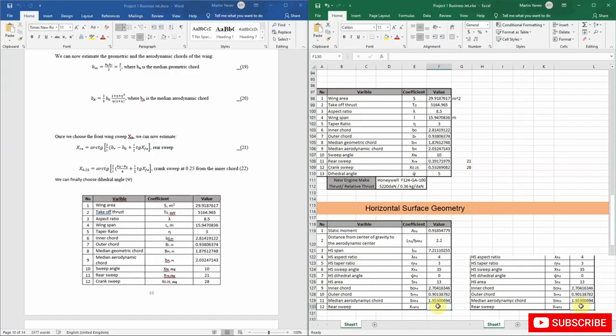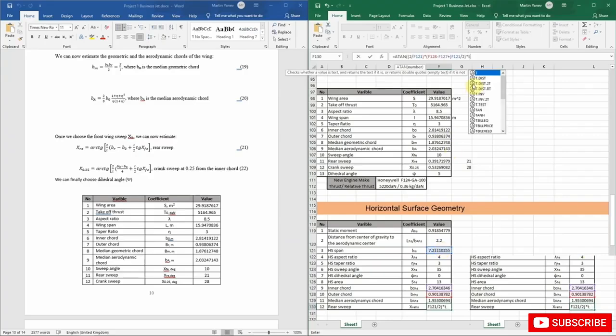So the rear sweep, as from the equation for the wing, will be equal to arccotangent, so a tan, and then in the brackets 2 divided by L, and this actually should be in brackets as well, and this will multiply by BR, so we'll multiply this by BR minus B0, which is this one, okay, plus, in brackets, L divided by 2 multiplied by tangent of the front sweep, which we chose to be 35 degrees, okay?